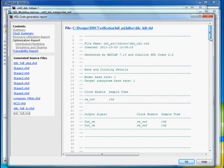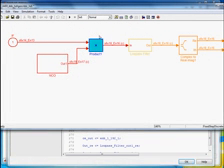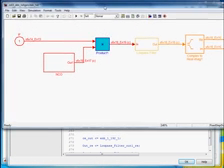So here we're looking at an example of the generated code. You can see it's pretty well structured. You can see that the naming of the signals corresponds to the blocks within the original Simulink model. And then you see these links embedded throughout the generated code. So by clicking on these, we can browse back to the model corresponding to the block of the model that corresponds to that generated HDL code. So that gives us some traceability going back.